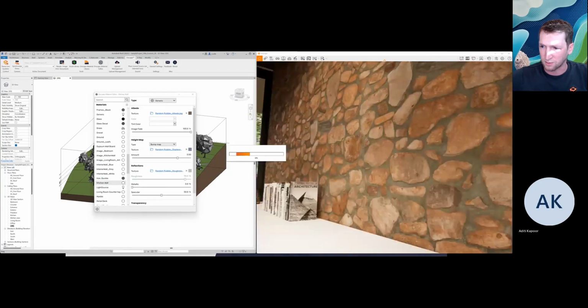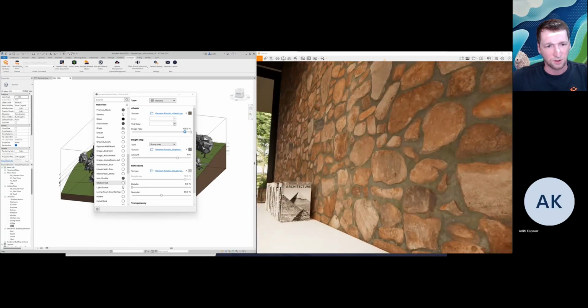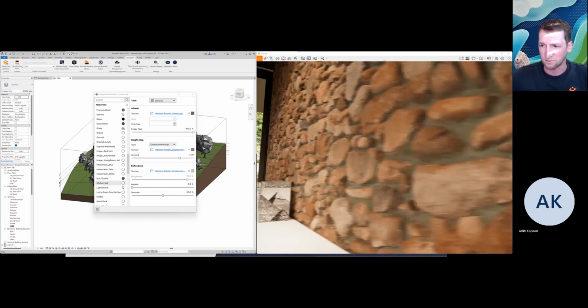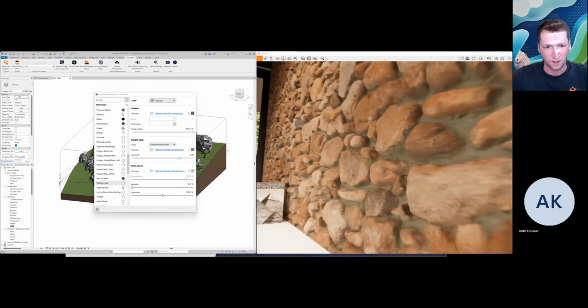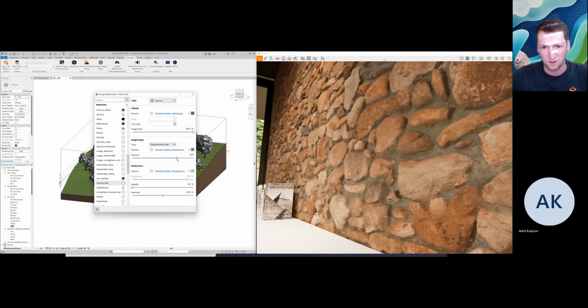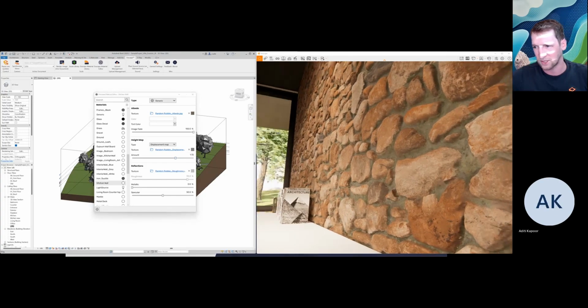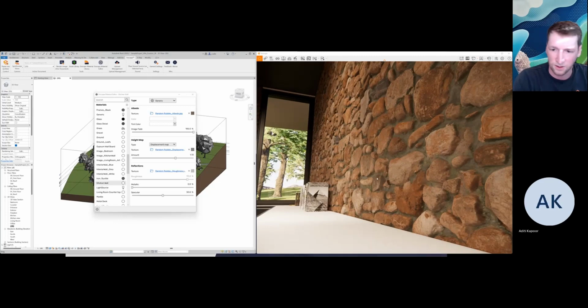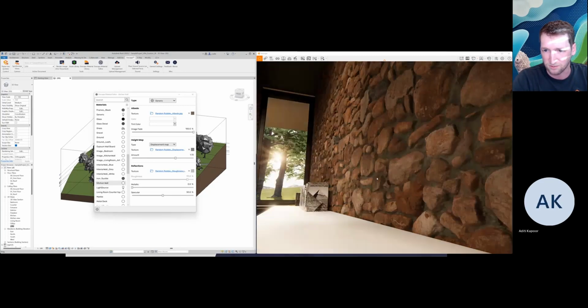And now this is where the real power of it comes in. So we'll click the drop down for the bump map and tell it to become a displacement map. Now we can see the real power of this displacement map here. And I can control how recessed that is just by interactively sliding my amount slider here left and right. So I can get a really nice shot on how I want that to look. And then I can control the Enscape camera to get a nice view on it.